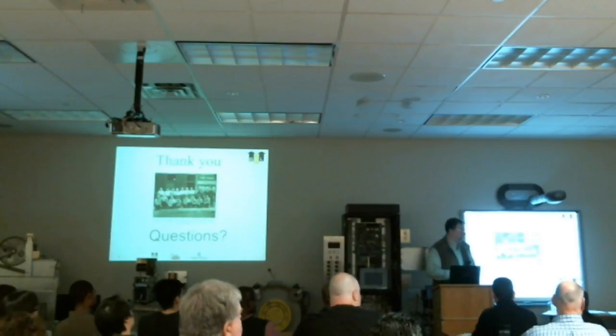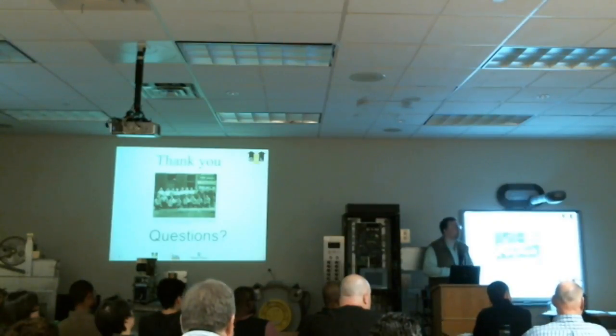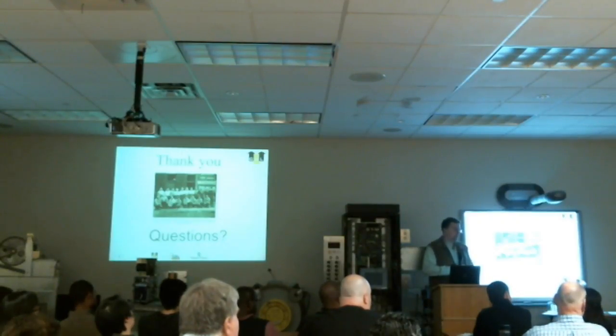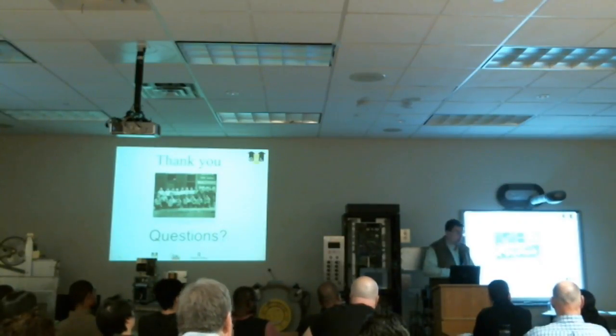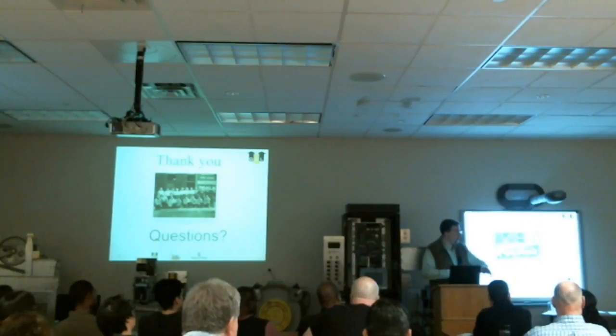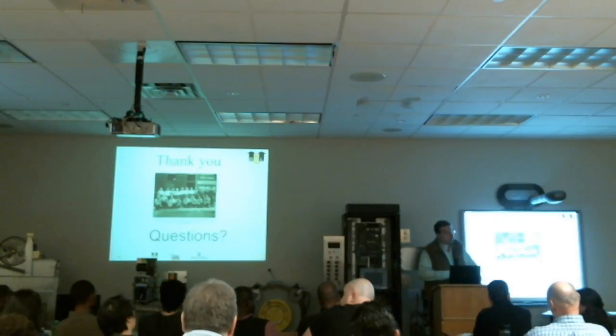The reason why I asked is that guys have contacted us and said, yeah, we have prints, but they're not for this job. And the way the old relay logic was, it was unique per job. There was always something different about what they did per job. Most manufacturers have job-specific prints. That was the same question we brought to the DOB: what happens if you have a controller in building A which is the same as building B? Can I take the prints from one, even though it's the same vintage controller, and use them on another building? They were also hesitant, and they didn't really give us an answer. By current code, if you don't have job-specific prints on the job, you're in violation, period.